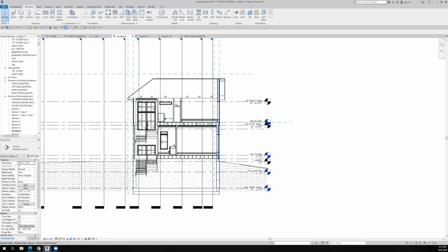And generally the wall is not wide enough to distribute the loads onto the ground. And that's what the pad footing does, it takes the loads and distributes them over a wider area, which allows us to build houses, for example, on soil that isn't really good bearing soil by using that pad footing. So we're going to put a pad footing in.